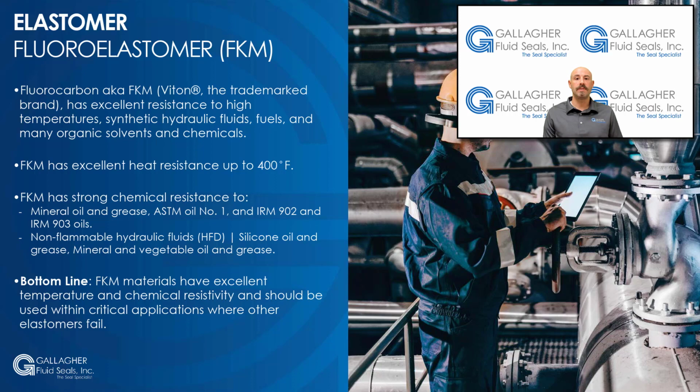Low temperature resistance is not favorable, and for static applications is limited to about minus 15 degrees Fahrenheit, although certain compounds are suitable down to minus 50 degrees Fahrenheit. Under dynamic conditions, the lowest service temperature is between 5 degrees Fahrenheit and 0 degrees Fahrenheit. FKM has excellent heat resistance up to 400 degrees Fahrenheit and higher temperatures with shorter duration.